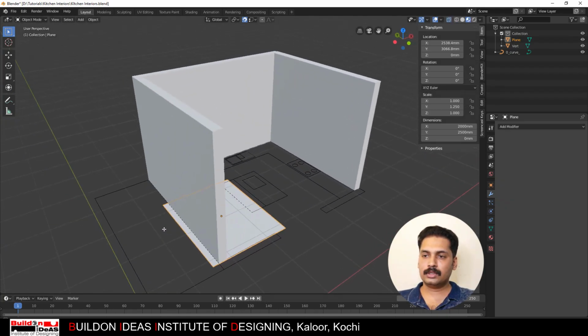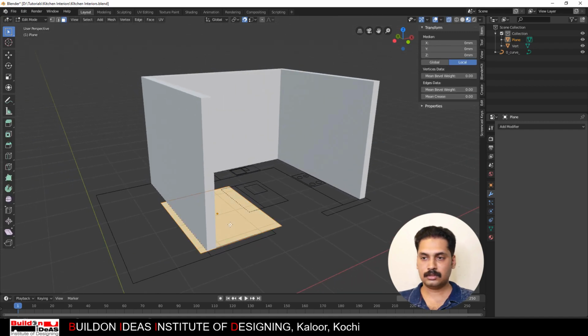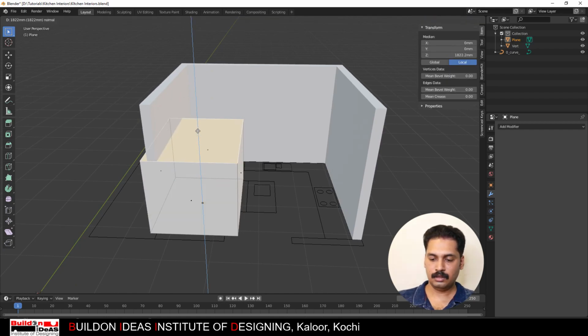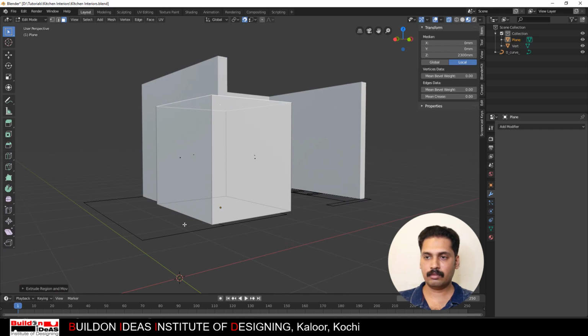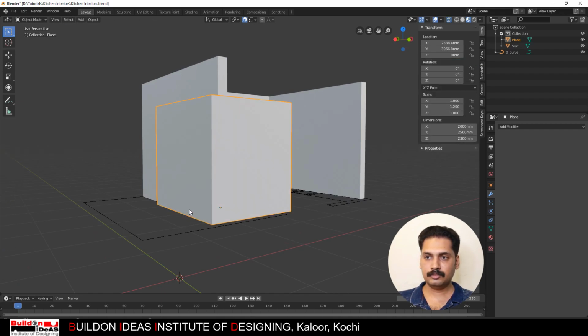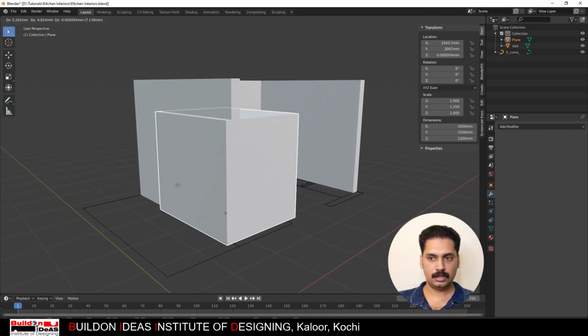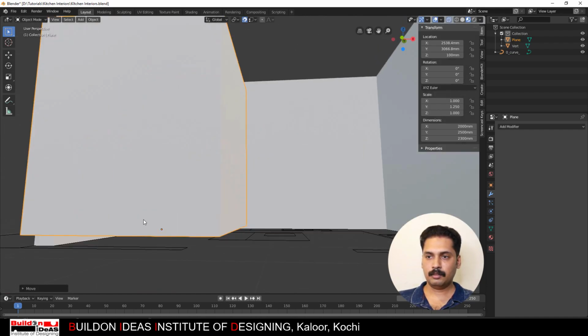Okay, now I'm just going to extrude this plane into a box by clicking on face mode, clicking on this face, and then extruding it by 2300 millimeters, because I am going to create a sill out here of around 100 millimeters. So I'm moving it above by pressing G, and in the Z direction I give 100. So now it's positioned 100 millimeters above.